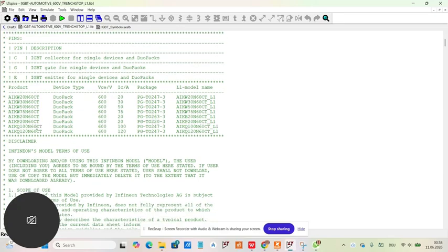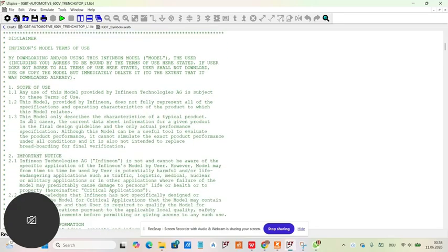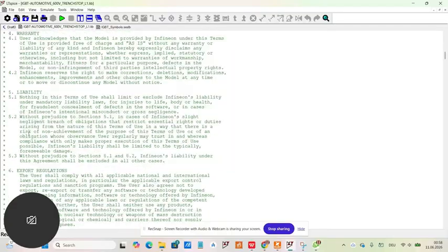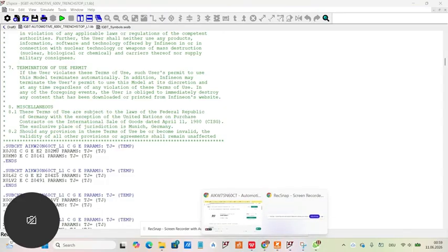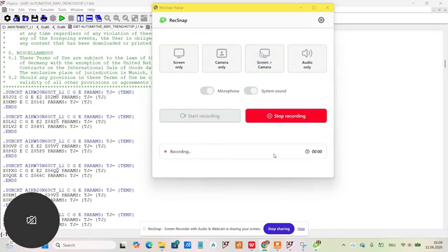AIK, don't choose any type. Make sure you locate that particular transistor. So we need to scroll down. These are the transistors .sub CKT. So these are the various transistor models that are present in that package. You see their pin configuration, the collector, gate, emitter. For this one, AIKW20N60CT. Is it what we are looking for?